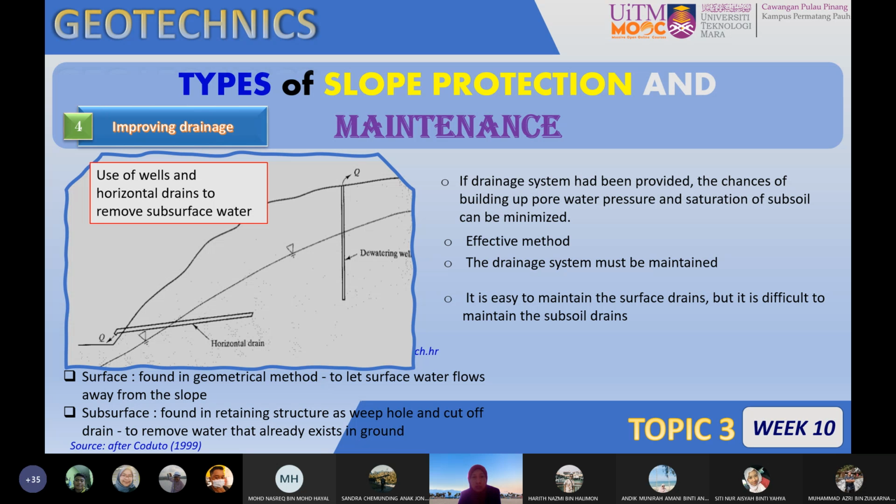So if you have some clog of dry leaves, you can remove it easily. However, if you have dry leaves inside the weep holes, that is very difficult to take out. That's why it is suggested that you do frequent or periodical maintenance work, just to make sure that the drainage is well maintained and functions well to allow water to flow out. Again, when we provide the drainage, we reduce the hydrostatic pressure.